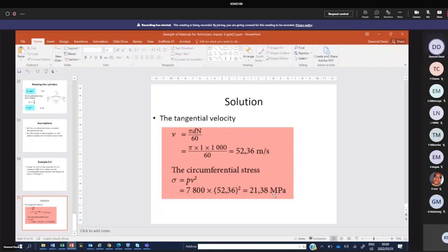How will the guy go inside? You can't do welding on the circumferential cap, so you use a temporary fastener, what they call an inspection hole. It's a disc big enough for a man to go through. They bolt it along the circumference. You see all those bolts on the bus wheels, about 12 bolts along the circumference. It's also a very good example of what I'm trying to show you. So you have some covers that are not welded, for obvious reasons, and they are secured by means of bolts.